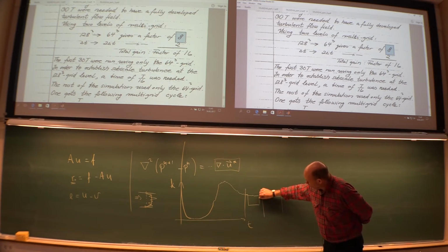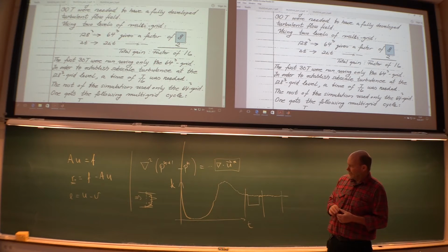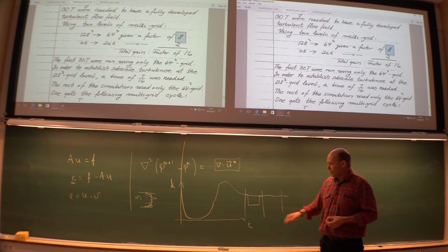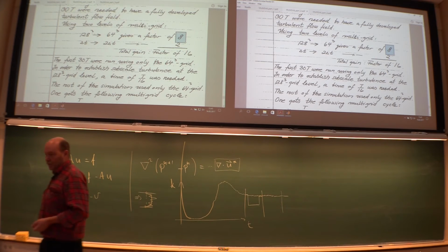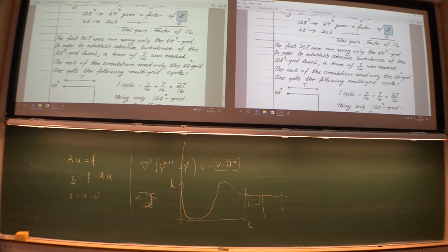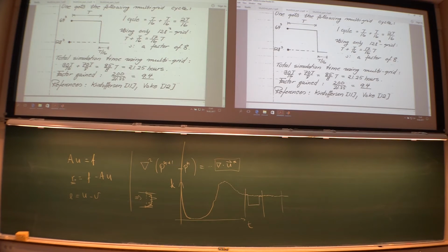Then I had to jump up to the fine mesh and simulate some time steps so that the new turbulent structures reorganized correctly, and then do another sample. Then I could reduce the cost quite a lot, actually a total gain of a factor of 16. So absolutely possible, yes, but it was sort of tricky.